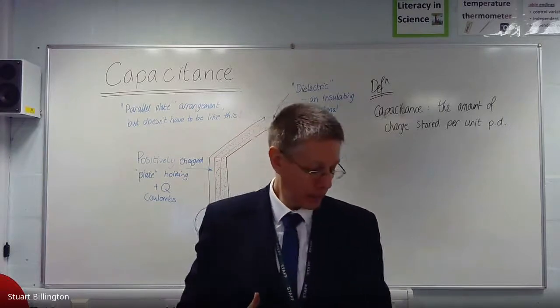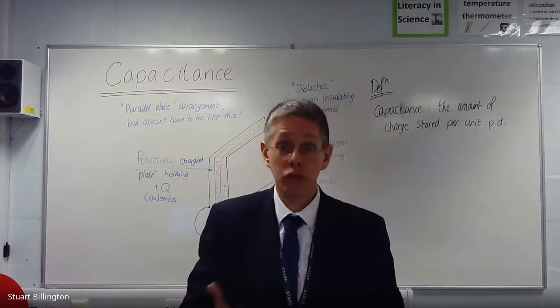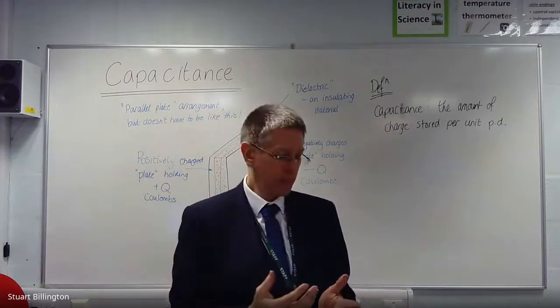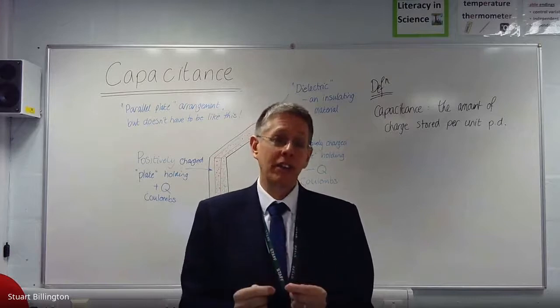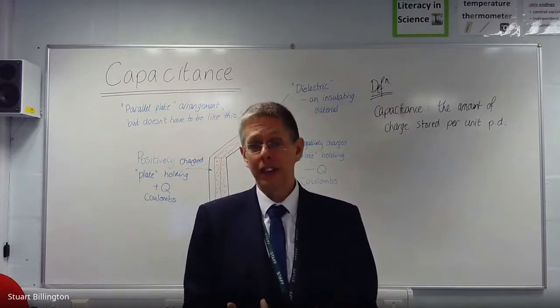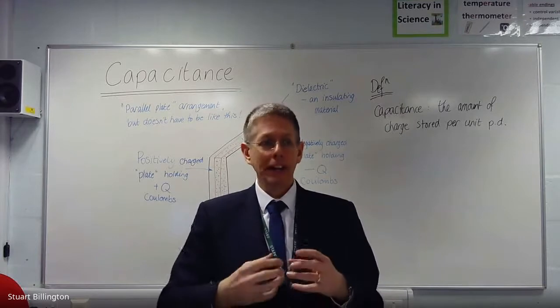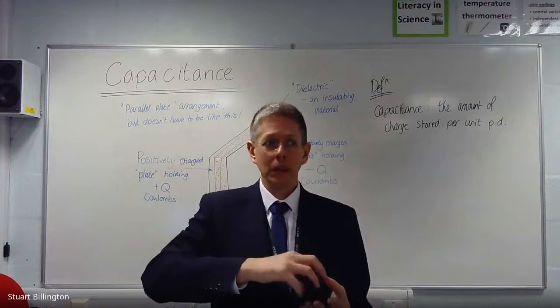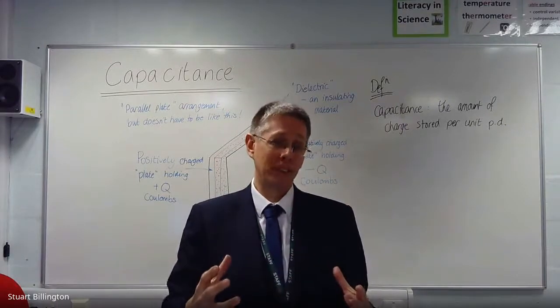And if you accidentally wire it up the wrong way, electrons really will flow straight across the dielectric as if it's not even there. And you'll get a very, very large current inside the capacitor, which will have a heating effect on the dielectric. And it will first melt it, and then it'll vaporize it. And then as the liquid turns into a gas, it will expand very quickly.